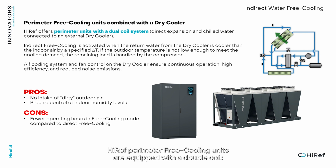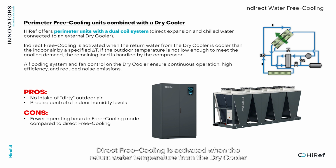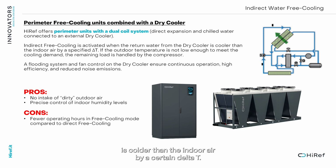HiRef perimeter free cooling units are equipped with a double coil, one direct expansion and one water-cooled, connected to an external dry cooler. Direct free cooling is activated when the return water temperature from the dry cooler is cooler than the indoor air by a certain delta T. If instead the outside temperature is not low enough to meet the load, the remaining portion is covered by the compressor. What are the pros and the cons of this solution?